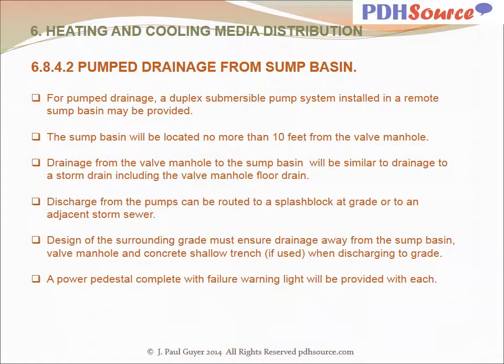For pumped drainage, a duplex submersible pump system installed in a remote sump basin may be provided. The sump basin will be located no more than 10 feet from the valve manhole. Drainage from the valve manhole to the sump basin will be similar to drainage to a storm drain, including the valve manhole floor drain. Discharge from the pumps can be routed to a splash block at grade or to an adjacent storm sewer. Design of the surrounding grade must ensure drainage away from the sump basin, valve manhole, and concrete shallow trench if used when discharging to grade. A power pedestal complete with failure warning light will be provided with each.